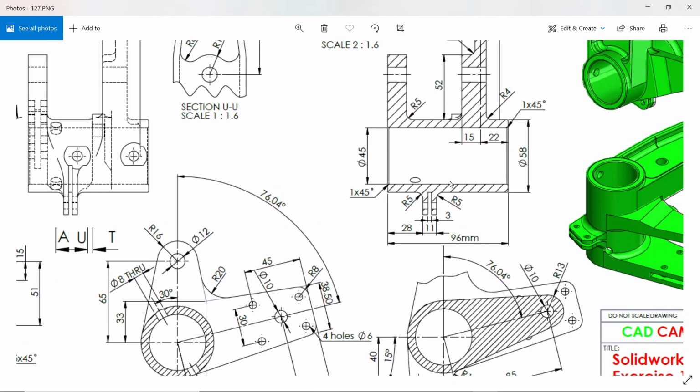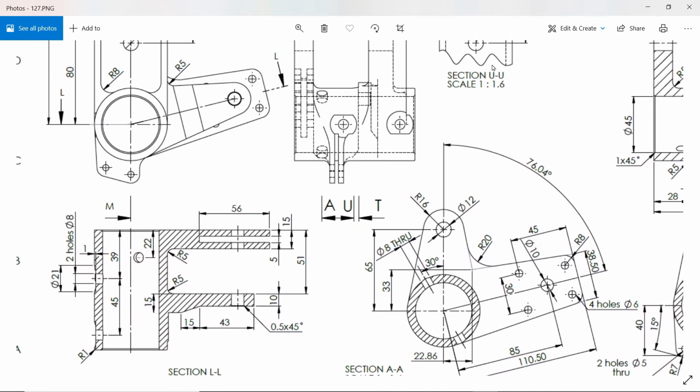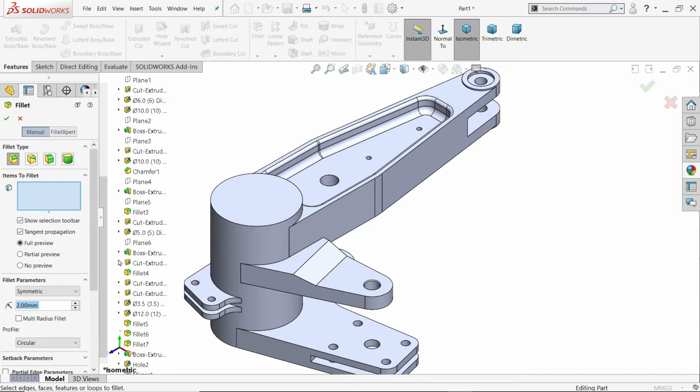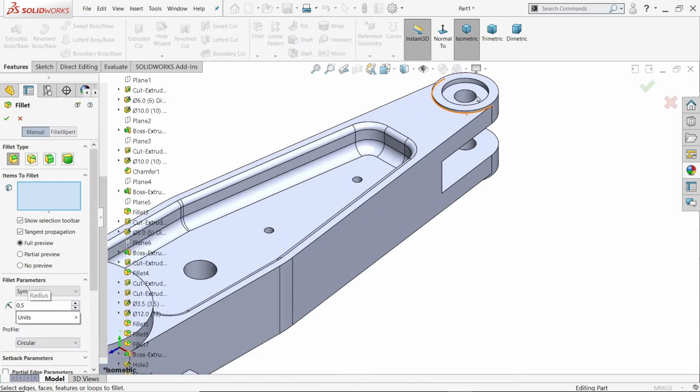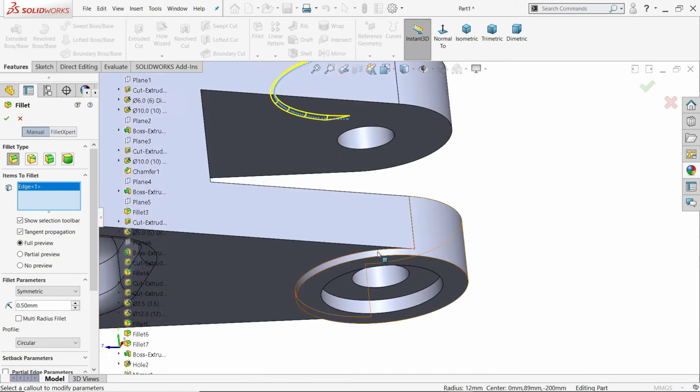and we will create this center hole 45 diameter, 1 chamfer at both corners, 1 millimeter, and there is a radius. This corner R1. Activate radius 0.5. You forgot to mention this.